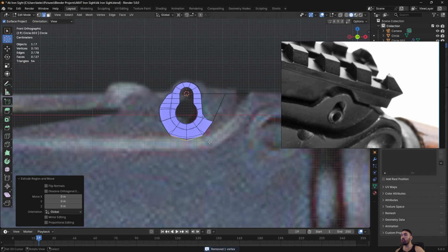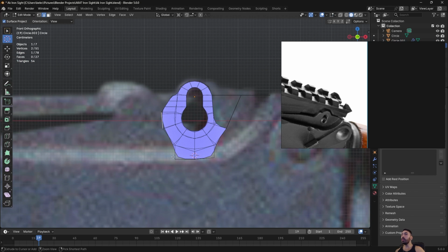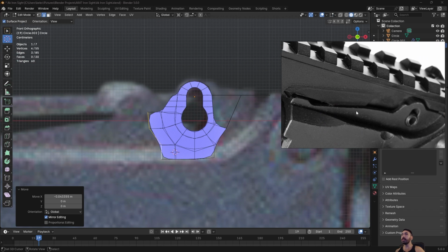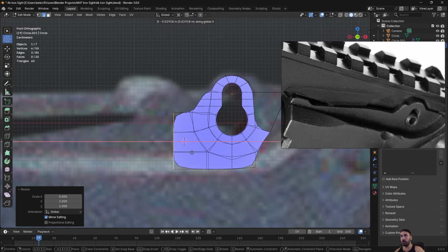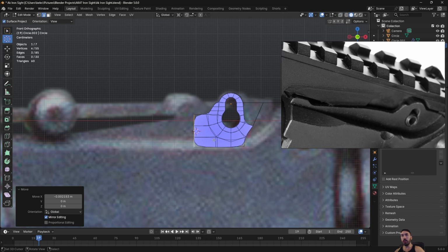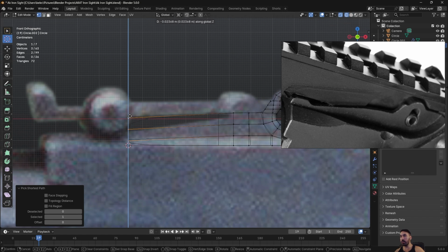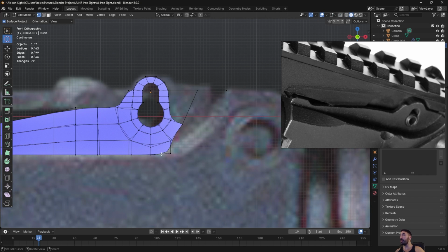First, let's use this geometry to get down to the floor here. We're going to extrude these 2 edges, and then these 3 edges over here are going to be used to create this little surface, and we're going to extend that all the way to the back there. So we just extrude them out a little bit. We scale them to 0 on the x-axis. We bring them to around here somewhere, which is going to be the middle of the flat part. Then we extrude them one more time, and then we can extrude them again, and at this point they're supposed to start going downwards. So let's just leave that here for now. We're going to take care of that later. First, let's do something about this part here.